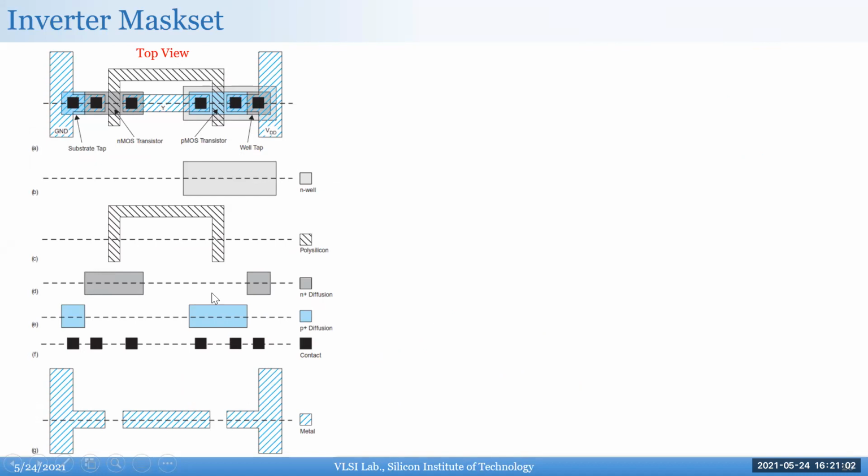And obviously, as I was explaining to Sumant earlier, if you have 1 million of these in your chip, you'll have all 1 million devices, with polysilicon in this mask, N-wells in this mask. So you only have the same number of masks no matter how many devices, right? The N-well for all the devices will be in the N-well mask, so when they take the N-well mask, they'll do the N-wells for all the devices at the same time, and then they move to the next layer.